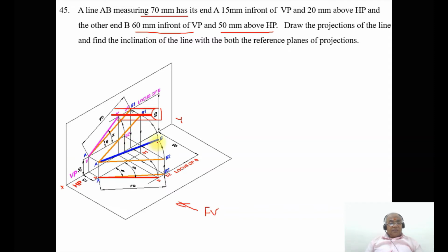So as we start rotating capital A, capital B2, which is in space, what happens to the image as you look from the front view? That b2 dash which was here is also rotated such that it will go into the locus of B in the front view. So that is what we have shown here. This capital B, this is the position where it is joining with b dash. Till where you have the locus of B, to such an extent this capital B can be moved or rotated. So this is how you will be able to analyze this particular problem by using 3D analysis.